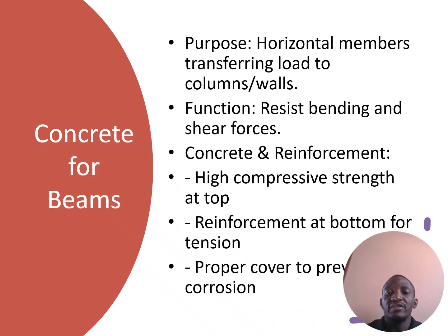Function. Let's look at the function. It resists bending and shear forces. Concrete and reinforcement: high compressive strength at top and reinforcement at bottom for tension. Proper cover to prevent corrosion.